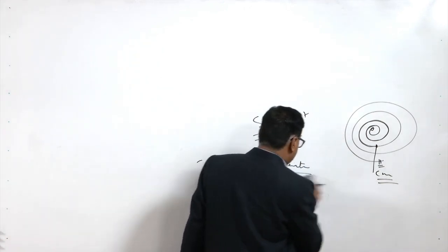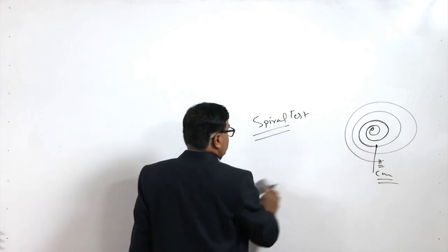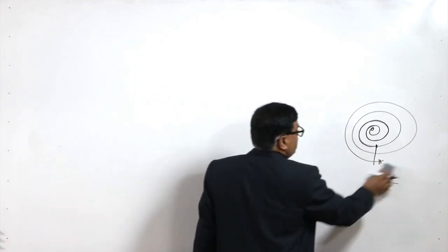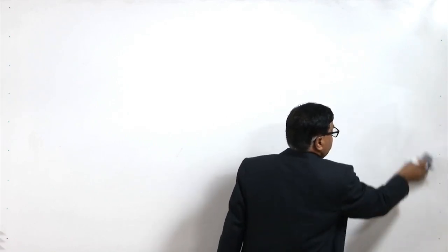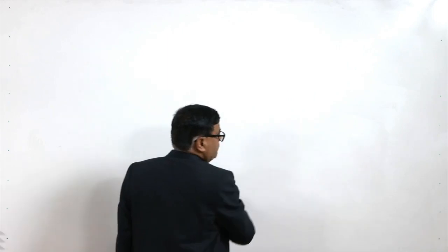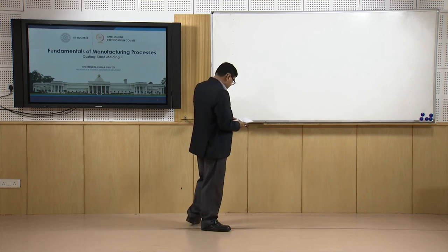It is important to avoid certain defects in the castings, especially defects like misrun, which are formed when the fluidity is limited. In that case, some zones and regions of the mold are not filled in completely by the molten metal due to the lack of fluidity.